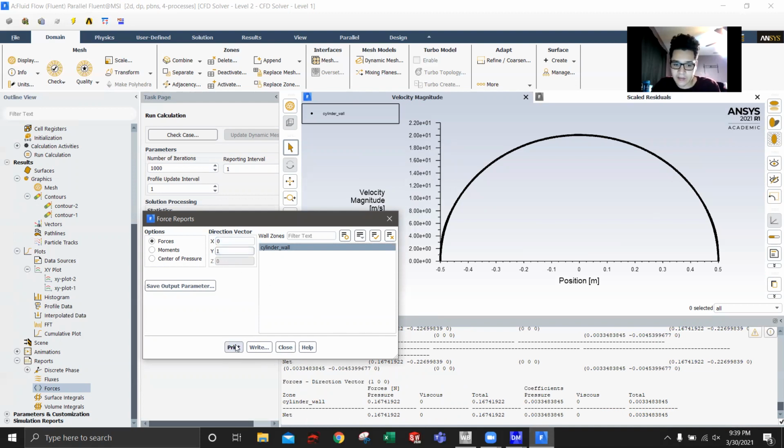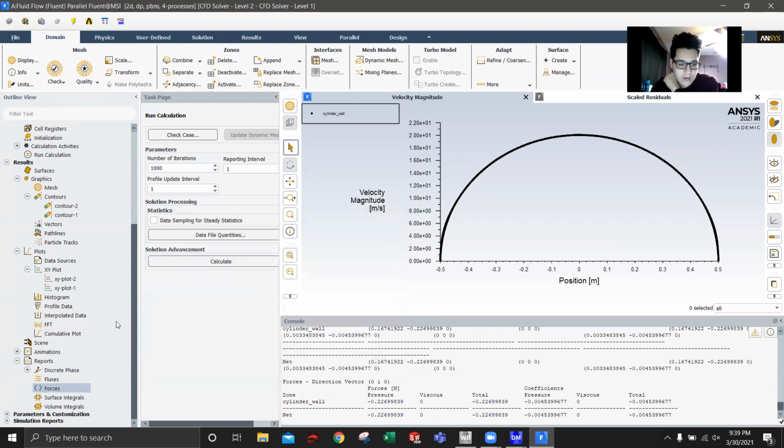You know, we can't get exactly 0 in the simulation. It's not perfect. So then going in the perpendicular direction, which would give us lift, and same thing, pretty close to 0. So just as we expect, where our lift and drag forces are 0 for the inviscid flow around a cylinder.